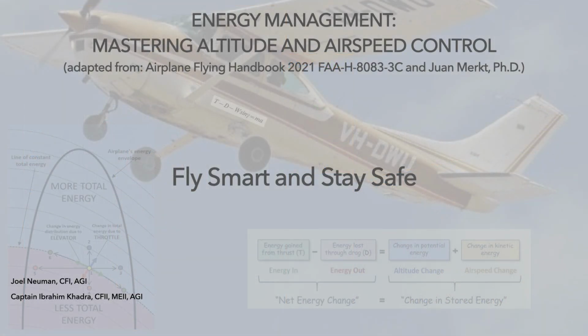In conclusion, when managing your airplane's energy, your goal is to detect, correct, and prevent altitude and airspeed deviations through the proper use of throttle and elevator inputs.